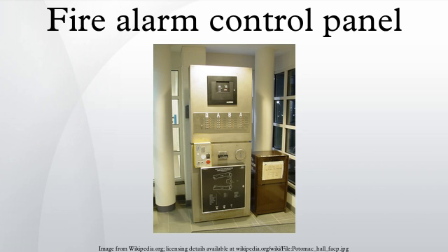A system reset is often required to clear supervisory conditions. A system reset does not usually clear trouble conditions. Most trouble conditions will clear automatically when conditions are returned to normal. On UK and most US panels, a silence or acknowledge is usually required before a system reset can be performed. Acknowledge. This function, also abbreviated to ACK, is used to acknowledge an abnormal situation such as an alarm, trouble or supervisory.